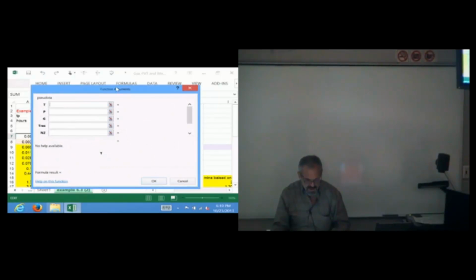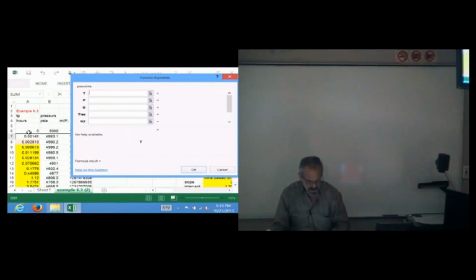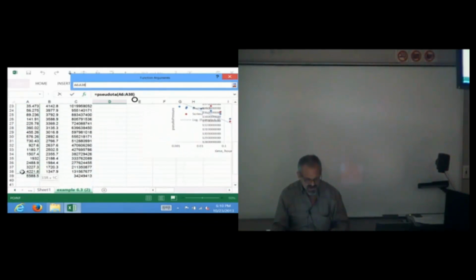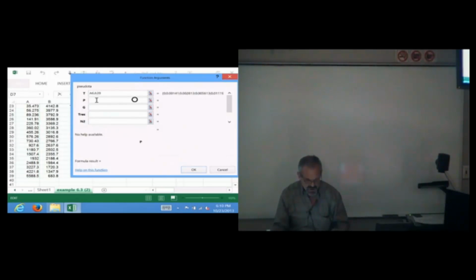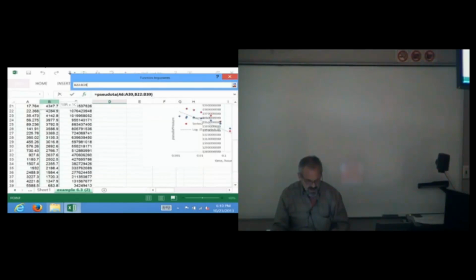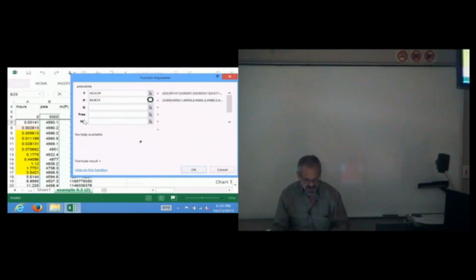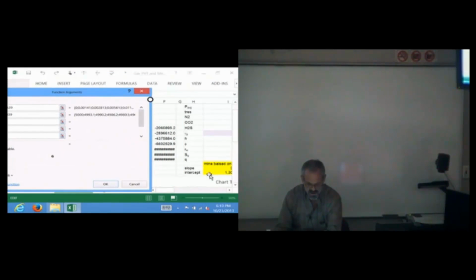It's going to ask for my time array. And I want to start at 0 because I'm going to capture that 5,000 pounds to calculate my initial pressures at. See, it's going to say T sub 1 is 5,000, and it's going to calculate my pressures at that. Then it needs my gas gravity, 0.6.